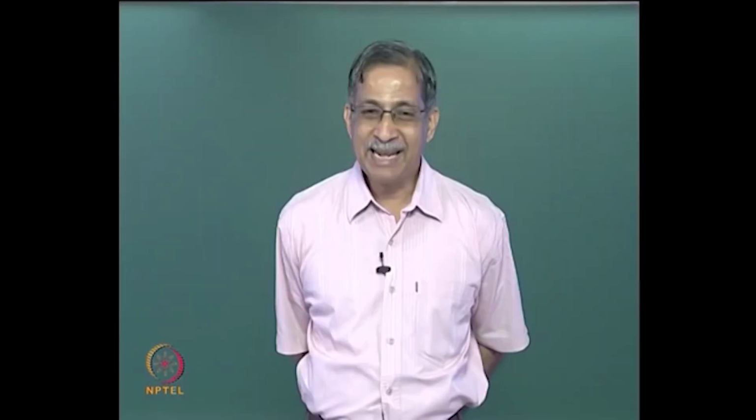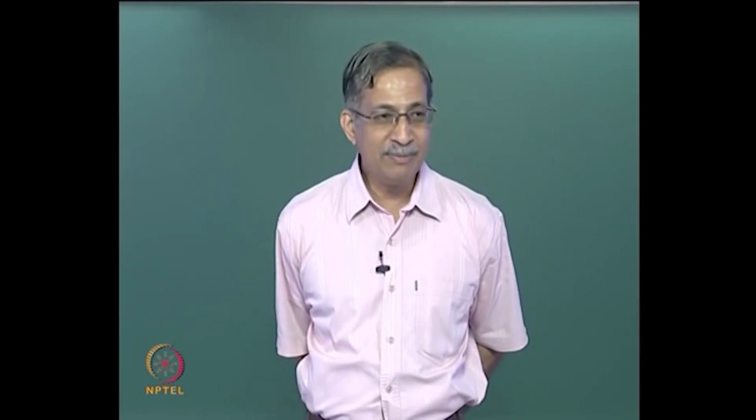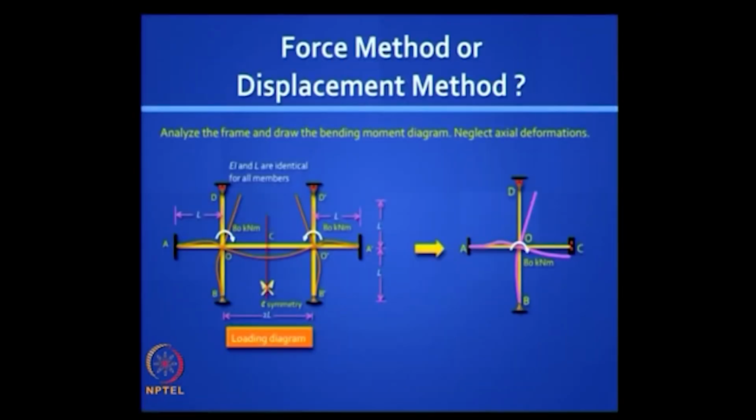Well, at that hinge support you have 2, at that guided roller support you have 2, you have a horizontal reaction also possible, and at the top you can have a vertical reaction 1, so that makes it 5. That makes it 5. What about the unknown rotations?